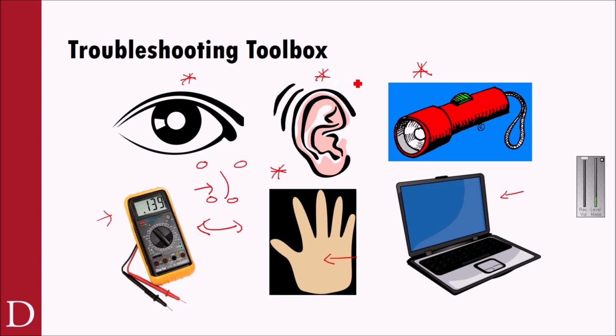A lot of times you can hear mechanical issues like bearings and things like that. Belts might squeak and bearings might grind. You can hear those things. And then, first and foremost are your eyes, getting out a good flashlight and taking a look. I've seen so many times someone grab a computer and hook it up to a PLC, only to discover, oh, by the way, a forklift ran into the side of that control cabinet, and that feeder that's going into there is actually dented or bent, or there's a pin broken inside.